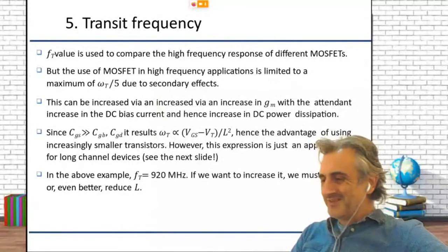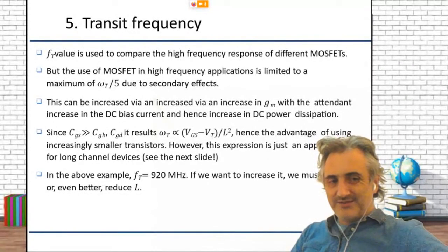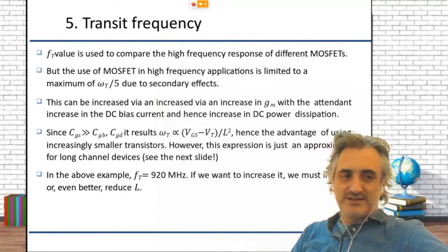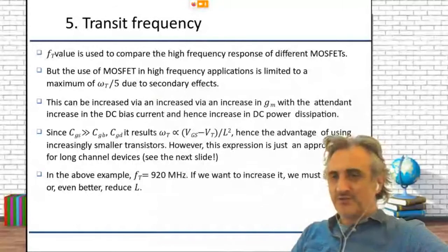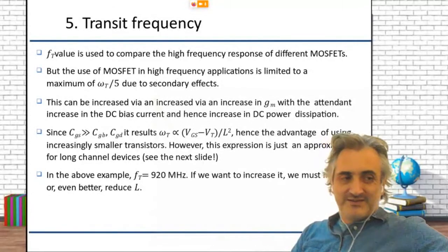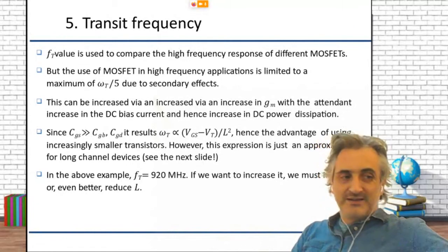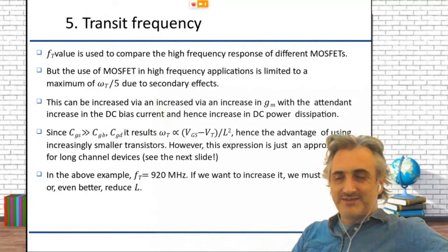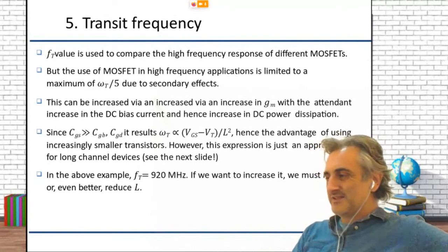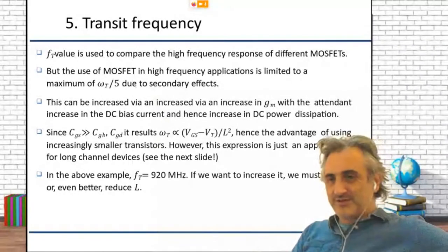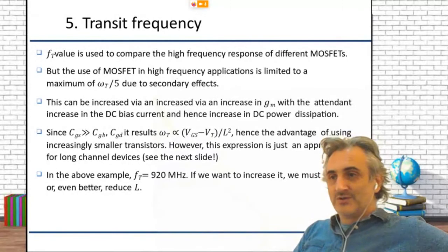So curiously, we are using the free band of Wi-Fi and Bluetooth and so on just because it's a frequency which is useless for long-range communications. Just because the water vapor in the atmosphere absorbs the signal so fast that it's very difficult to use it for long-range communications. So this is why it's free for short range communications.